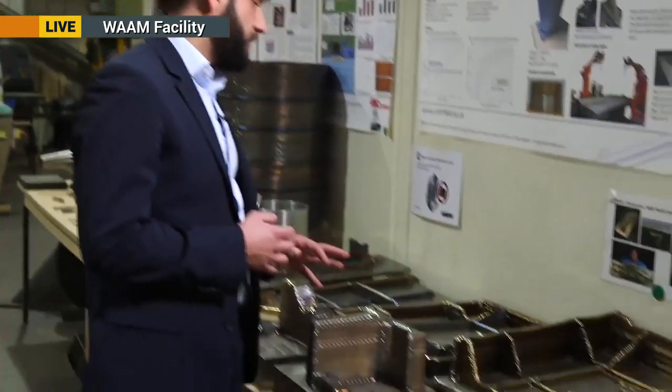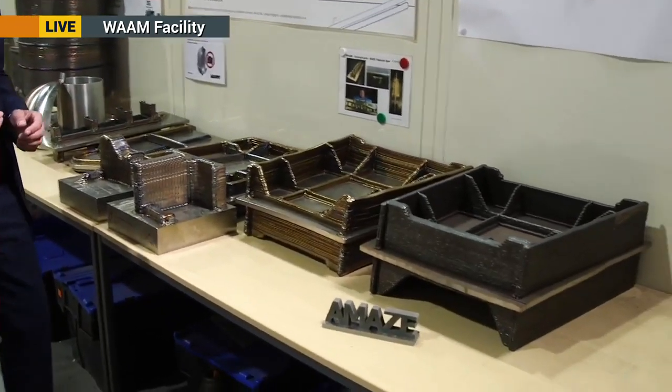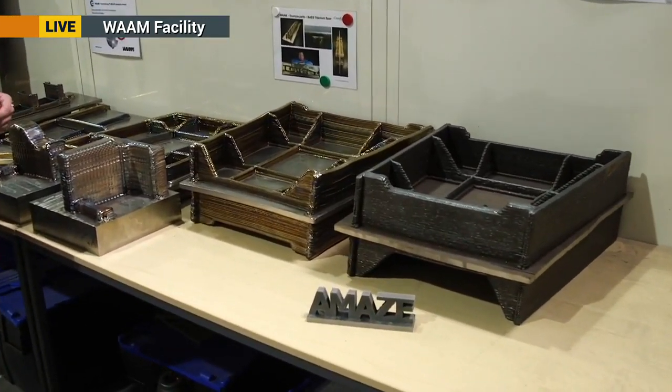Thank you, Chris. So as the name suggests, WAAM is based on wire instead of powder as feedstock. And this enables substantial scalability of the part that we can make. We can make them much faster. Instead of building at 100 grams per hour, we can, for example, build up to 15 kilograms per hour. We can make these parts as big as you want, as I will show you later, and of course in a much cheaper way. Here we've got only a few of the many demonstrator parts that we've made throughout the years for our research partners.